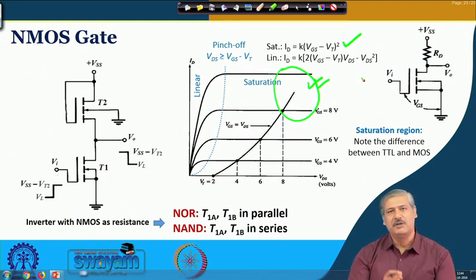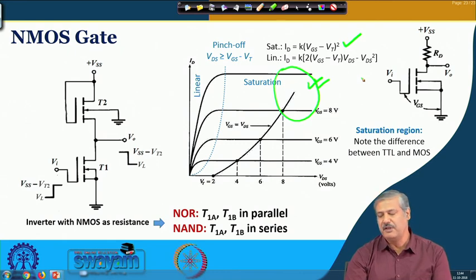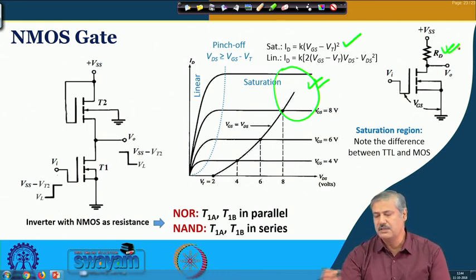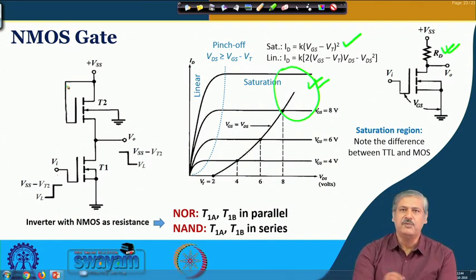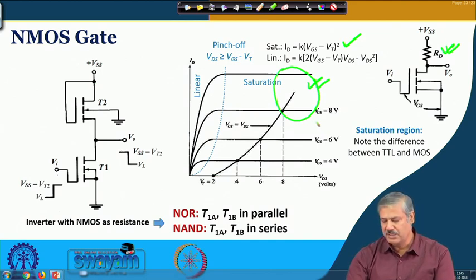In NMOS based logic development, manufacturing resistances is a problem, because the resistances are very high, and this high resistance manufacturing takes a lot of space. So, instead of that, an NMOS transistor based load is used, with gate and drain connected in this manner, which offers an approximately linear characteristic.